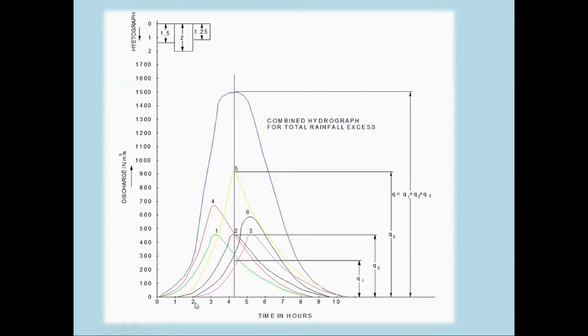Now the third rain, because for this third rain I am plotting, it is 1.25 hours, but presently I am plotting only the unit hydrograph, which is of 1 centimeter duration. So the third one, this was at 0 hours the first started, at 1 hour the second started, at 2 hours the third started. So this is in the pink color.